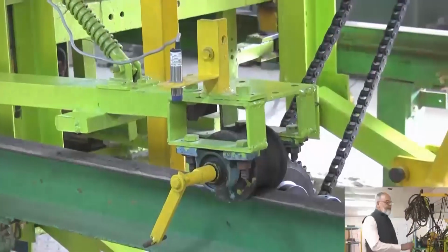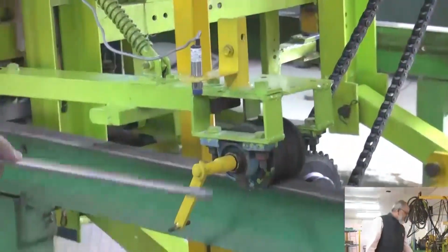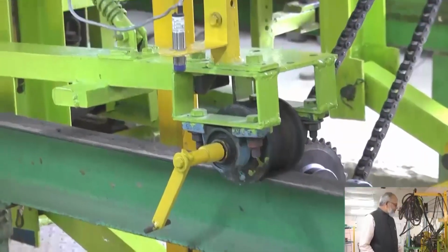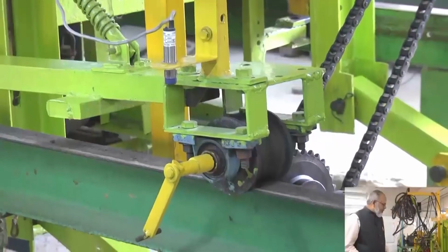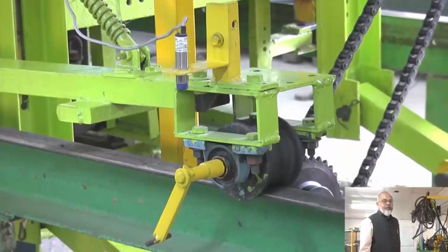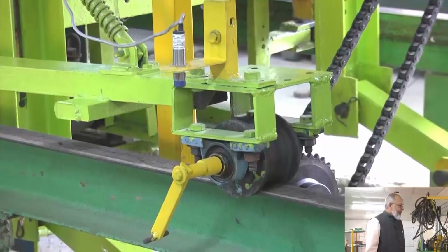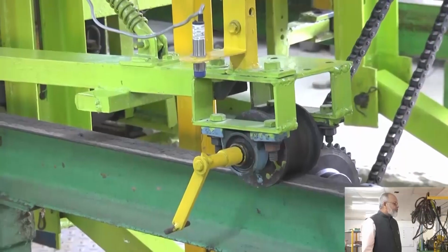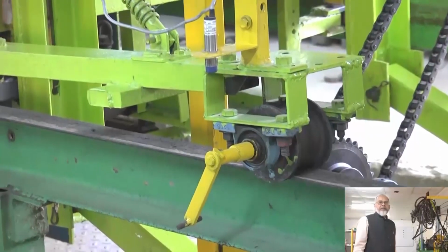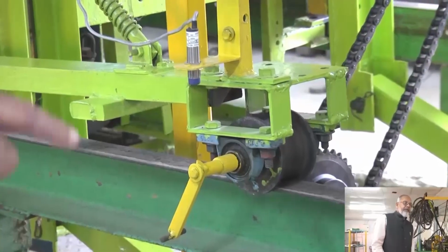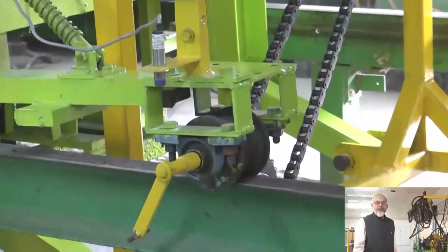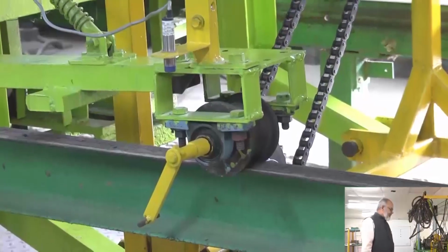When the wheel moves forward, the roller rotates, and when this bar comes close to the proximity switch, a signal is sent to the output. That output is stored in the computer. We measure the number of pulses and the corresponding time. The number of pulses divided by time will give you the actual velocity.